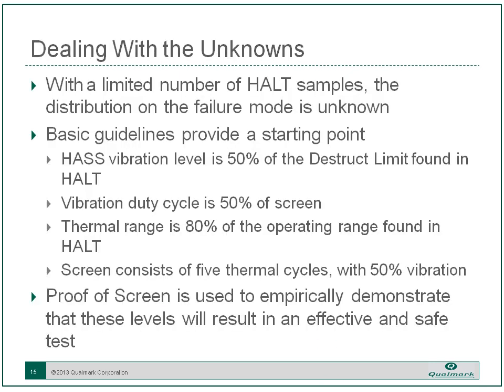So we've got some basic guidelines that we've developed as a starting point when you're setting up a HASS screen. And these are based on historical information and math and what's been shown to work in the past. And what we've found is we take what we have found for a destruct limit for vibration in HALT and reduce that by 50%.